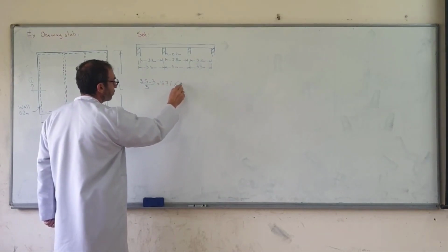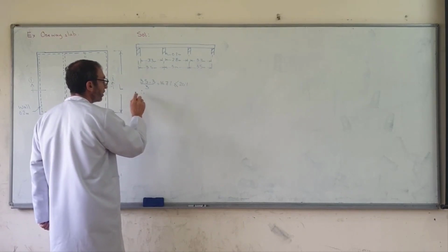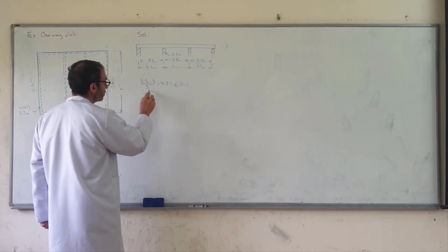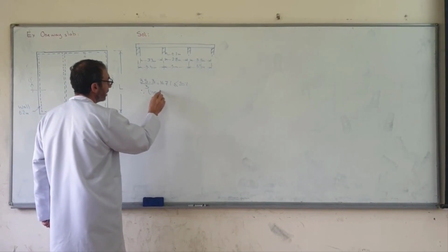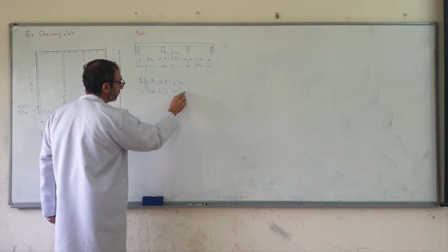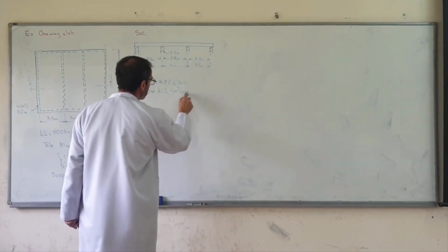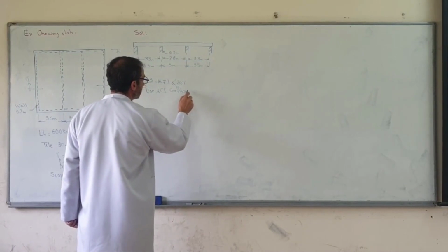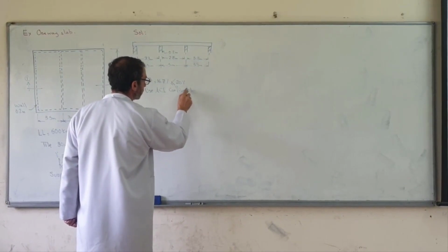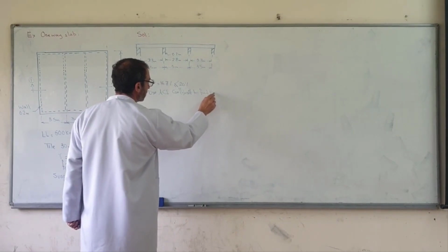This is less than 20%. Therefore we can use ACI coefficients to find the moment.